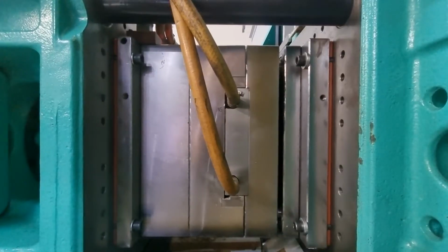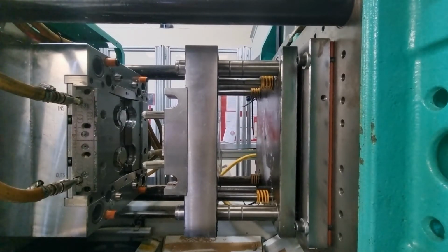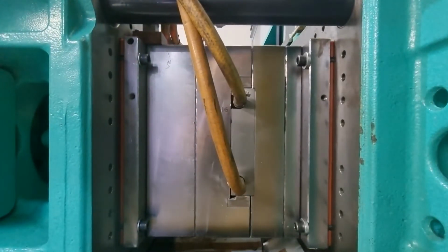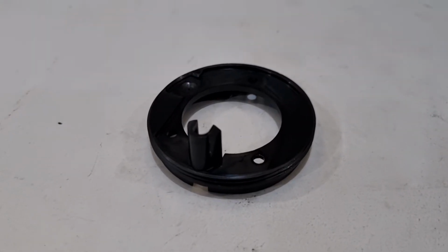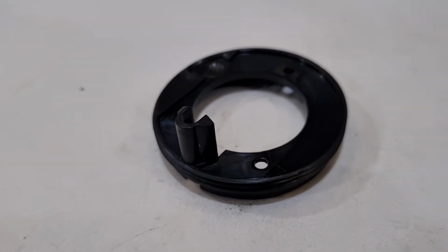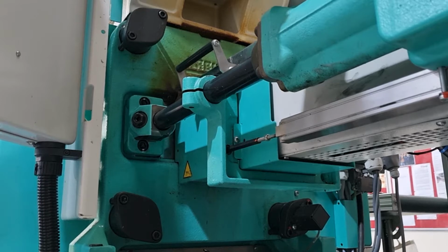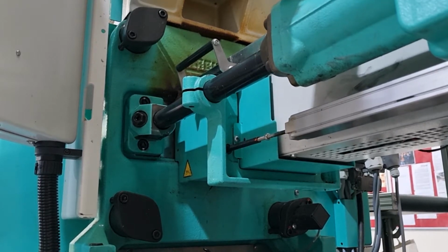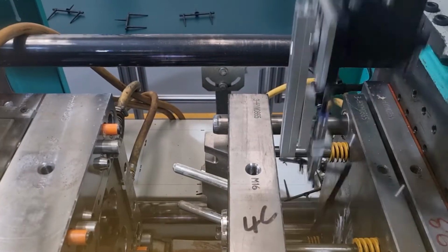Using this tool as an example, which makes light fixtures designed to replace their metal counterparts, the cold runner system is essentially a channel or channels that guide the molten polymer from the barrel through to the mould tool and into the gates which feed the core and cavity. Because there's no secondary heating element in the tool, the sprue also cools as the moulding cools, which has to be removed along with the part.